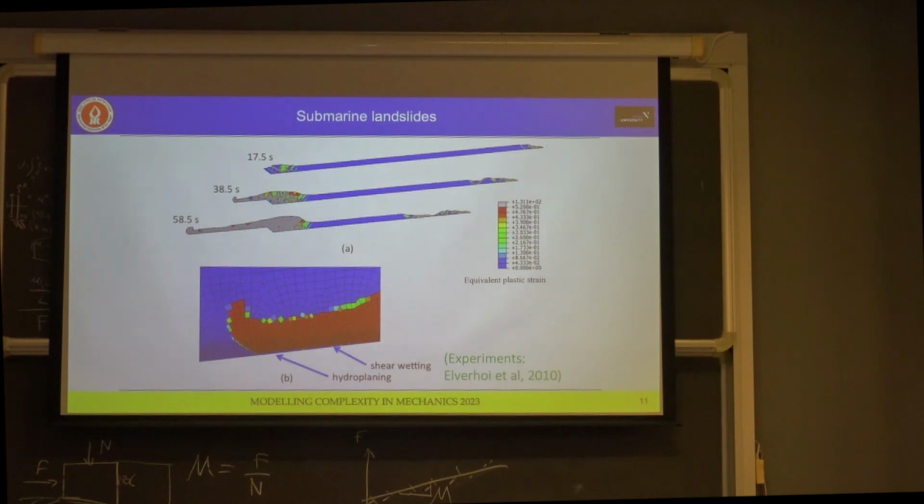So actually this tool can be really valuable, and if you ask what material model I have applied, it is the simplest: linear elastic soil with strain softening. If we apply a more advanced, more complicated model for soil, probably we can get better results.